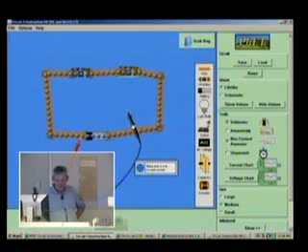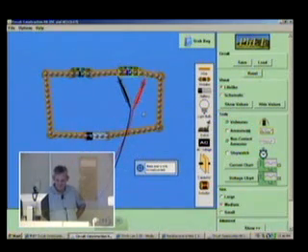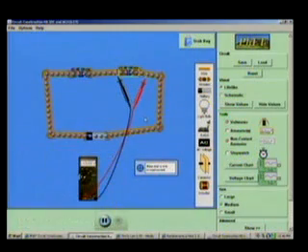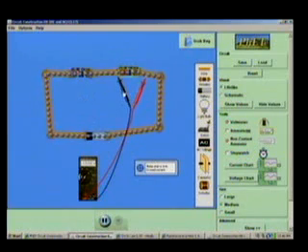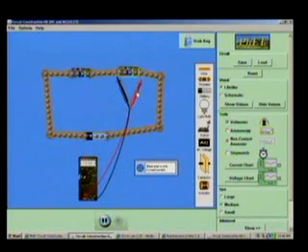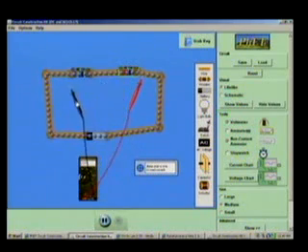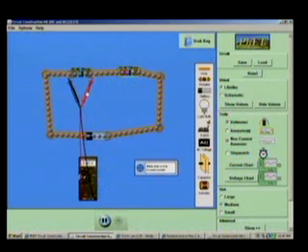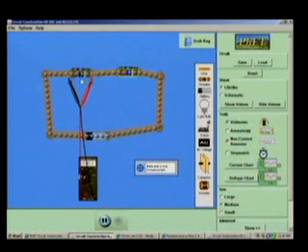All right. Now, since they're kind of upside down to this one, I'll put this here. The negative goes there. That goes there. What's he? Negative 13. What do you think the voltage is over here? All right, let's try this again. He's positive 18. This guy becomes negative 5, if I keep my configuration uniform, where I put the black where it's flowing out. Okay, he's negative 5. 18 plus negative 13 plus negative 5 equals what? 0. So the voltage stays the same.